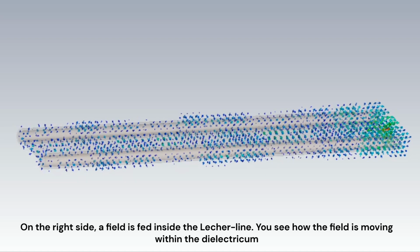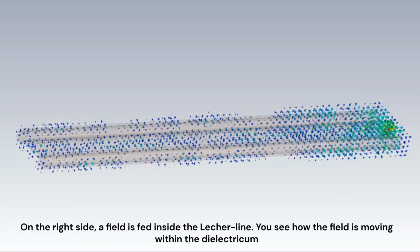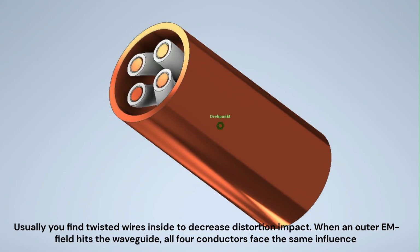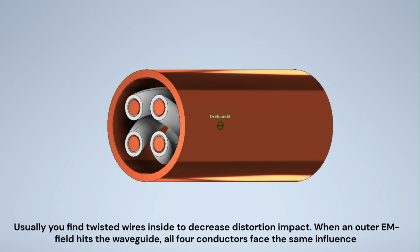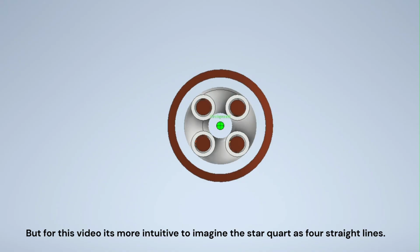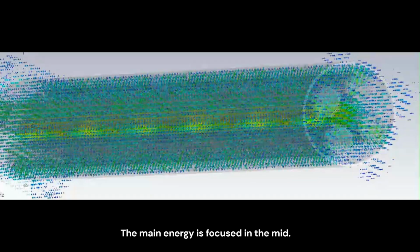On the right side, a field is fed inside the Lecher line. You see how the field is moving within the dielectricum? The next type is the star quad. You find this geometry mostly in measuring technology due to its robustness against distortion fields from outside. Usually you find twisted wires inside to decrease distortion impact. When an outer EM field hits the waveguide, all four conductors face the same influence. But for this video, it's more intuitive to imagine the star quad as four straight lines. The main energy is focused in the middle.